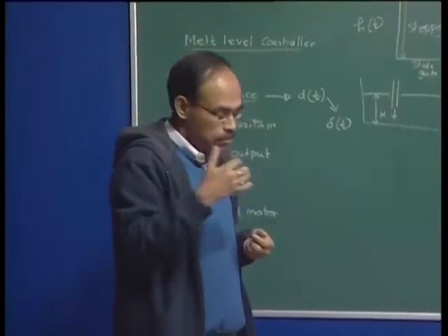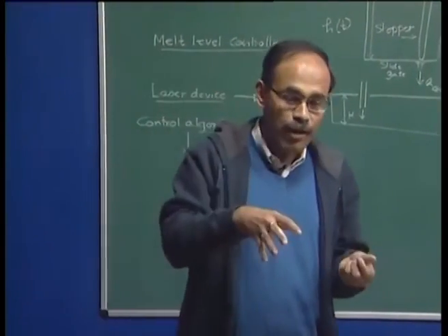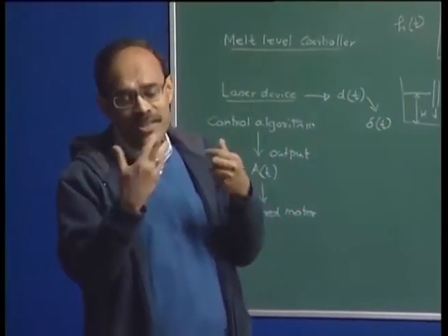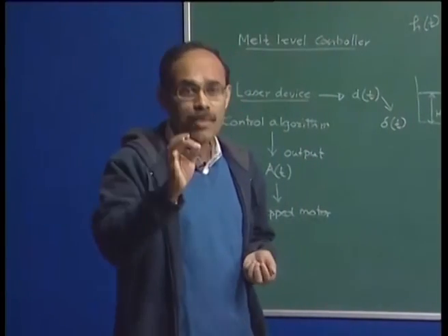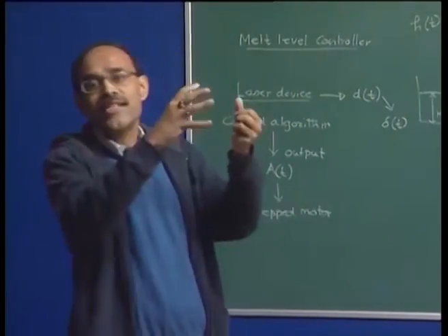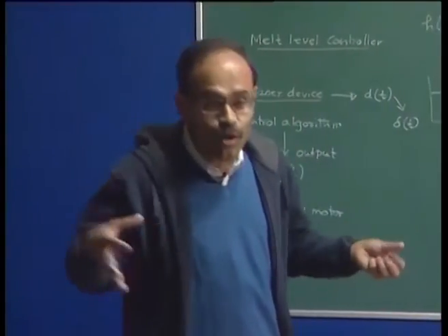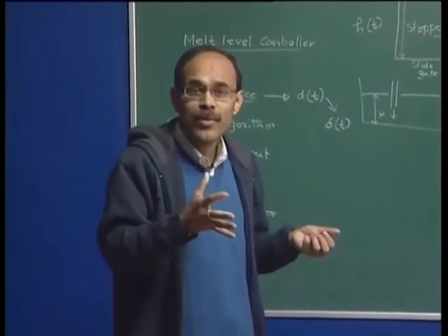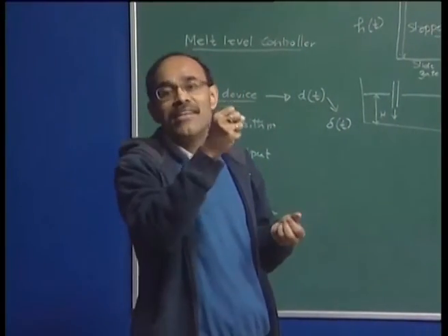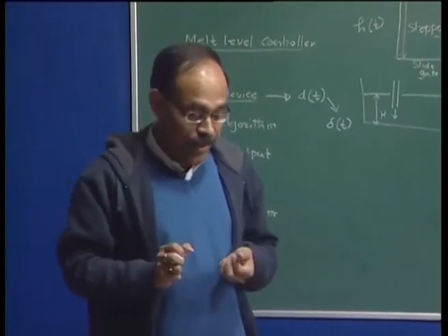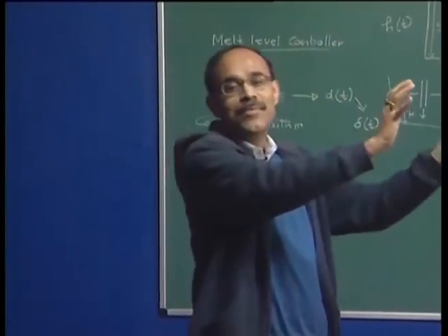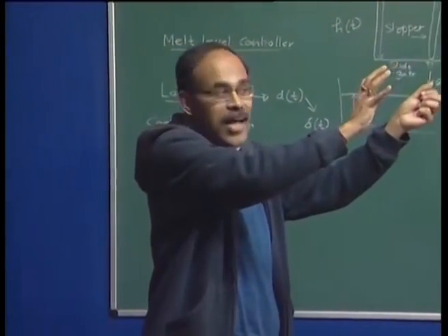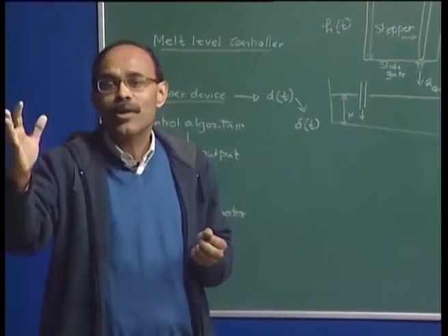And following ladle furnaces we can go for vacuum degassing, and subsequently we can go for inclusion modifications through injection metallurgy and so on. I have also mentioned to you very categorically that the more secondary steel making operations you incorporate in your steel making circuitry, the amount of effort is going to be increased, and as a result the cost of the final steel produced is going to be increased. So, today the trend is to carry out primary steel making, or mostly decarbonization, in the oxygen steel making converter, and then tap the molten metal and carry out all these operations in ladles.